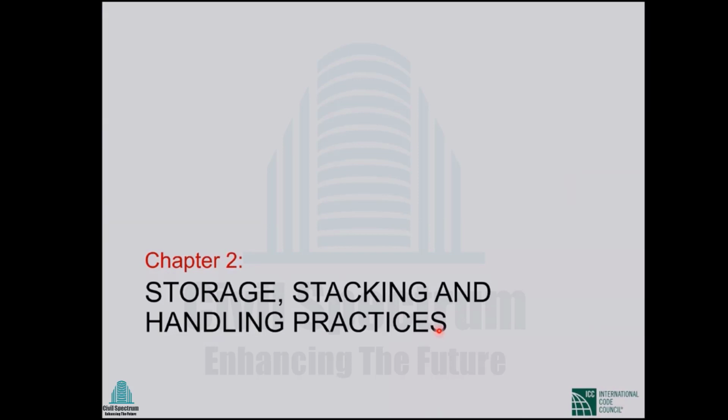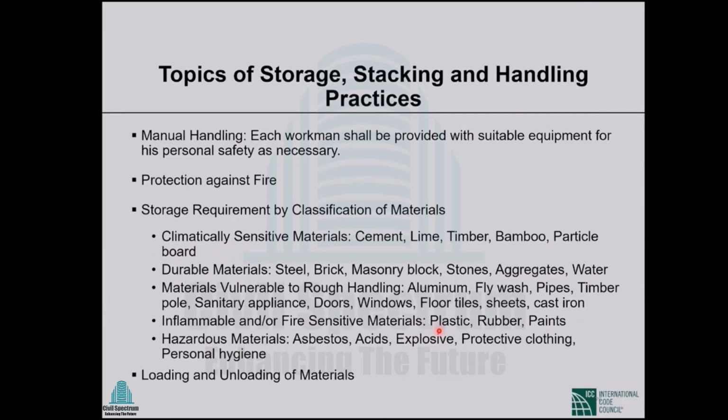Chapter 2 of this Part 7, storage, stacking and handling. This is also very detailed. I don't know how many of you know about this chapter. In this chapter, these topics are there. I want to specifically mention this classification. This is new. It was not there in the previous version. All the materials are classified into 5 classes. Climatically sensitive materials like cement: if you put it in a moist condition, you cannot use it anymore.